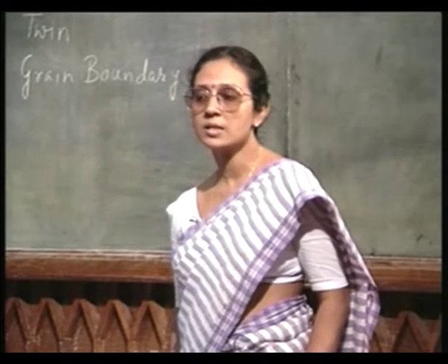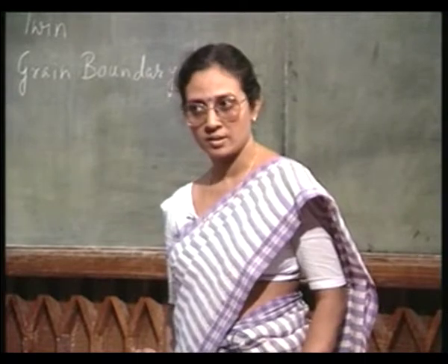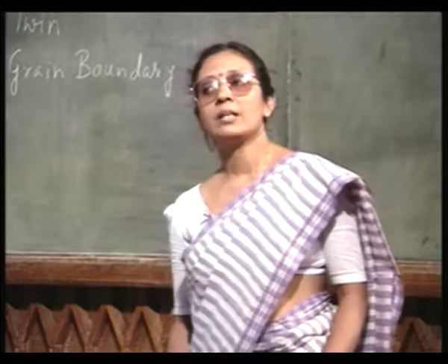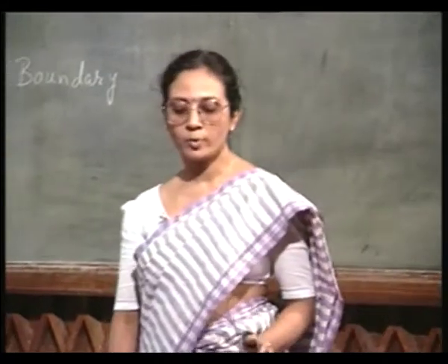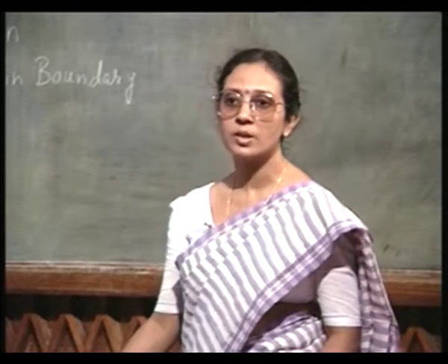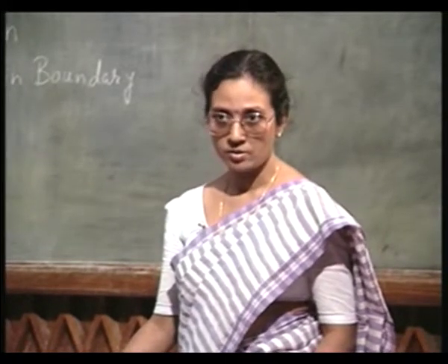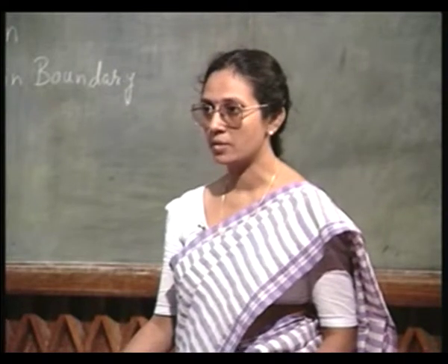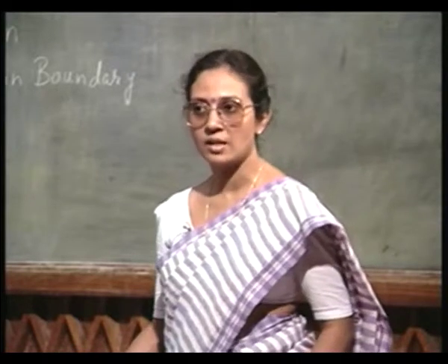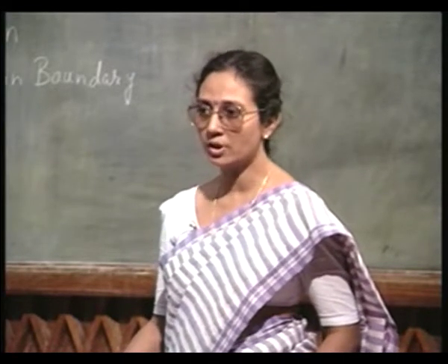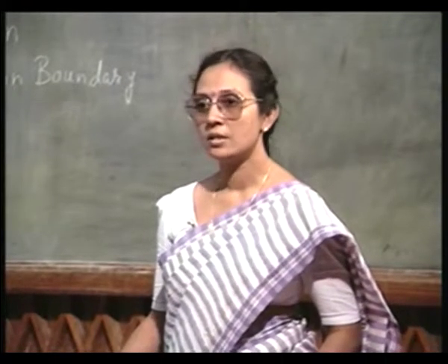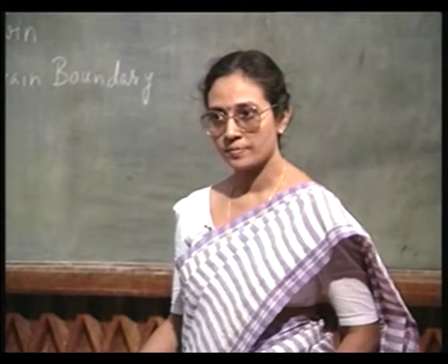So, the grain boundaries have a lot of defects. In fact, if you have polycrystalline material with sufficiently large grain, it is possible to cut from this material single crystal material. However, silicon crystal growth technology is sufficiently advanced, so that we do not have to bother about the materials which have such area dislocation, area defect problems.